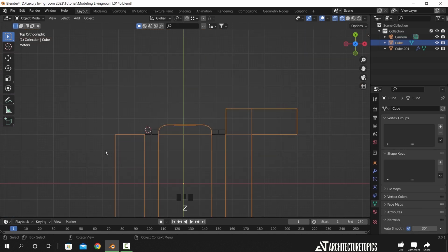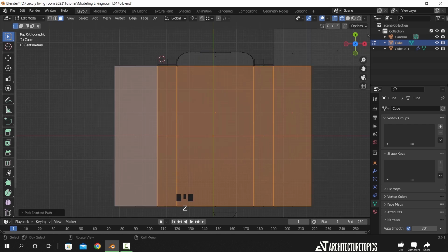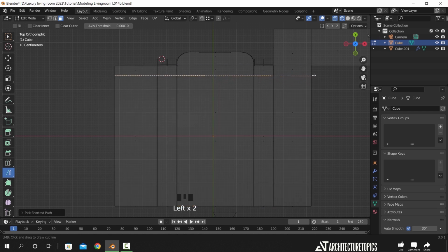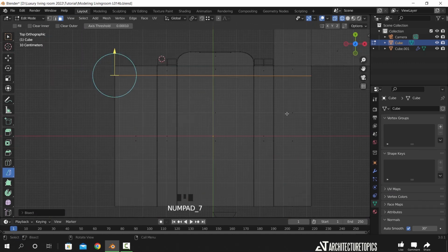Now for the ceiling, we should separate it from the start. However, things happened and now we can't add cuts to it, so I will use the knife to slice it into quads, then remove the faces in the middle to add new ones. The ceiling we have here is very simple with small extrusion to place some lights in it.